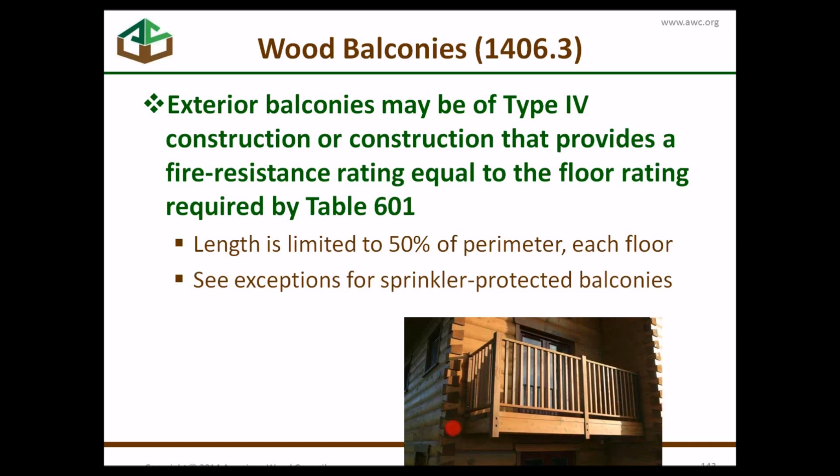The first one is you generally have to rate the floor of the deck the same rating as the floor that it's adjacent to in the interior of the building. Whether you achieve that with heavy timber or some type of 1 hour protection if it's required to be a 1 hour floor, it can be wood, but it has to have the same rating. You're limited in that case to 50% of the perimeter of the building, and there's some other conditions in 1406.3.